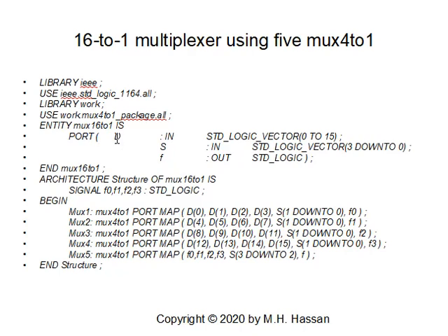Entity MUX16:1, I will define it. I have D, the input, here the D's will be 0 to 15, and I have the select line. I have a 4-bit select line, so it's 3 down to 0, and I have a single bit output in standard logic. I will end MUX16:1.